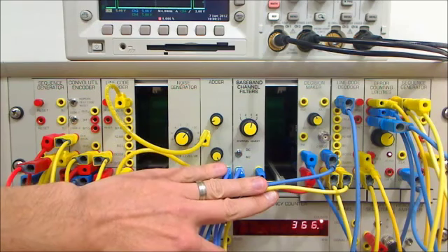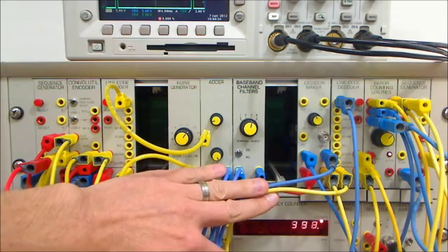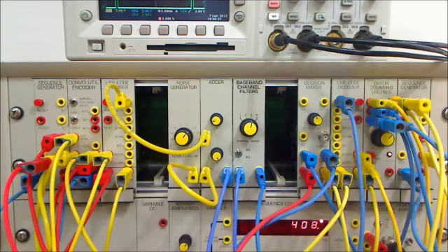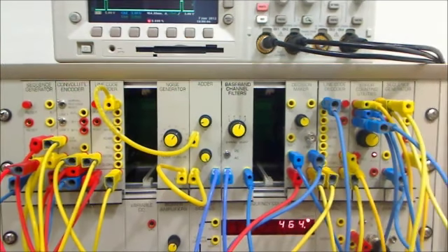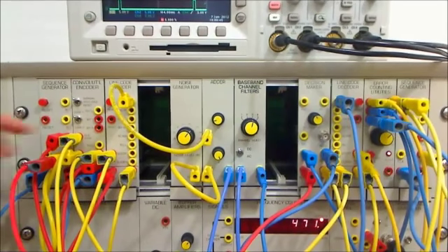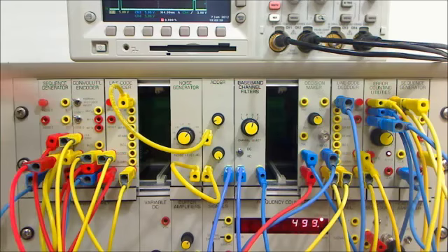And taking these measurements, as per the previous experiment, you plot the signal to noise versus bit error rate measurement curves, and the students are able to study the performance and develop a deep understanding of convolutional encoding using both systematic and non-systematic codes, which are selectable from the front switch, etc.